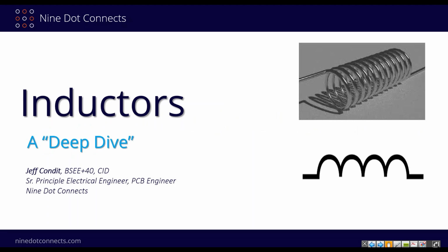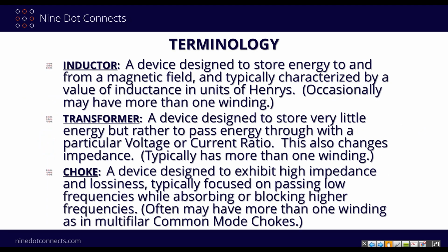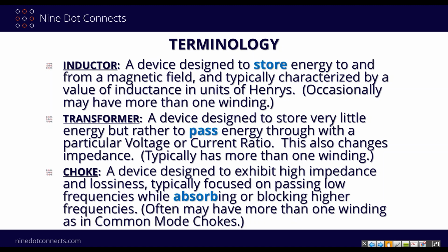Good morning, everyone. This is Jeff Condit with 9.Connects, and I'd like to talk today about inductors. So we'll start with a little bit of terminology. There's a lot to go through, so I'm going to keep booking it through here. First of all, there's three terms I'd like to talk about: inductor, transformer, and choke. An inductor is specifically a device designed to store energy to and from a magnetic field, and is typically characterized by a value of inductance in henries.